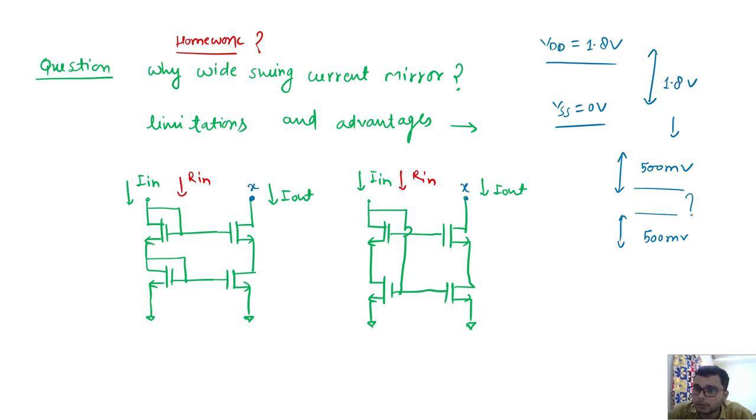Only 0.8 volt peak to peak is left to me. So whatever the gain of the transistor, you cannot apply a bigger input, because your swing at the output is limited. If you apply a larger peak to peak signal at the input, your output will be saturated. So there is no use of that.